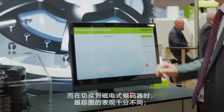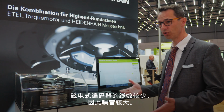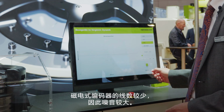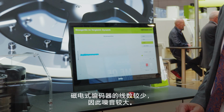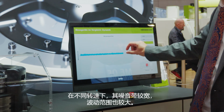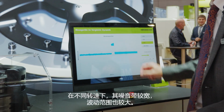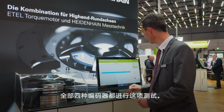But the trace looks much different when we switch to a magnetic encoder, which produces more noise due to its lower line count. This is the magnetic encoder installed at the bottom. Its noise band is much wider and fluctuates more under varying speed. This test can be performed for all the encoders.